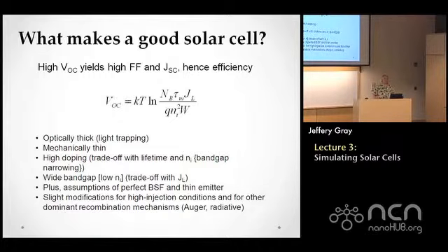JL is ideally going to be the number of photons in the solar spectrum whose energy is at or above the band gap of the semiconductor. Now it's hard to do that because as you get close to the band edge, the absorption isn't perfect. You can't have an infinitely thick semiconductor, and so some of the photons are going to pass right through the semiconductor without ever being absorbed.